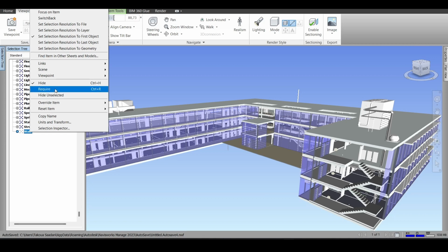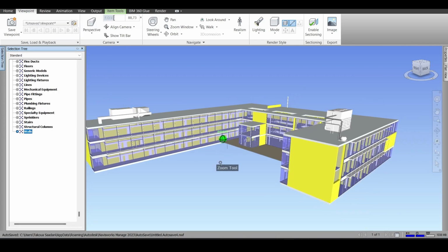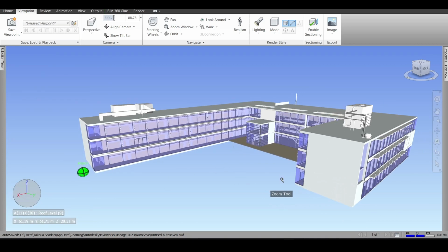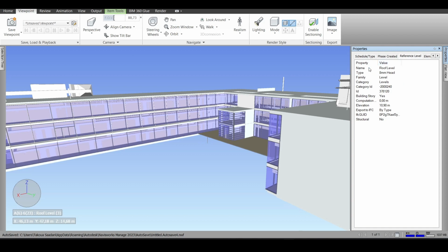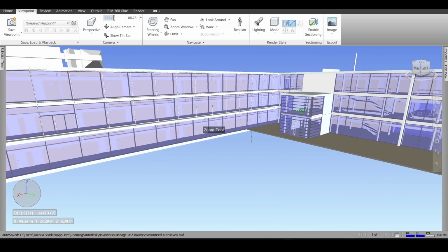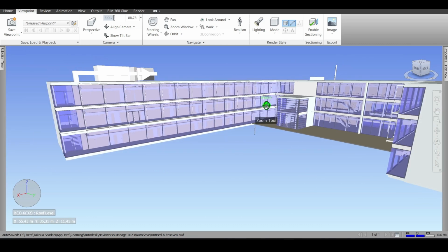Now I'm going to unhide the walls of the model, and yeah, let's, for example, select a pipeline and view the properties. All the data that we have exported from the modeling software, which was Revit, we can find it in here, in depth and details. That's why we make sure to set the proper export settings from Revit.